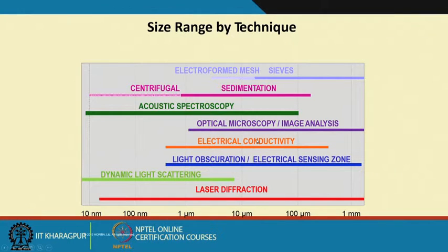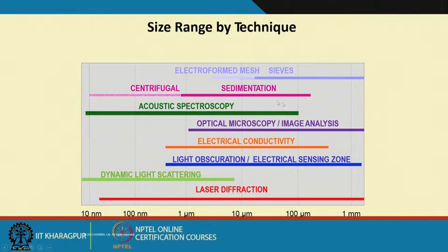are they really close to the size you are looking for while designing a settling basin? That means, why do you want to know the size of the particle? Because of how they travel in a fluid medium. So, I would say use a technique which is based on the sedimentation principle, because that closely relates to your process.